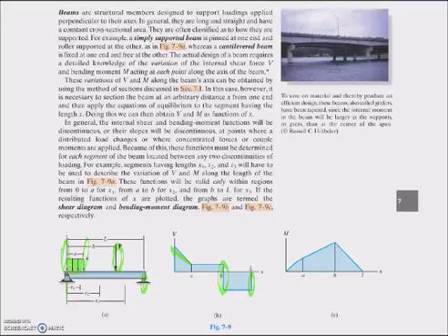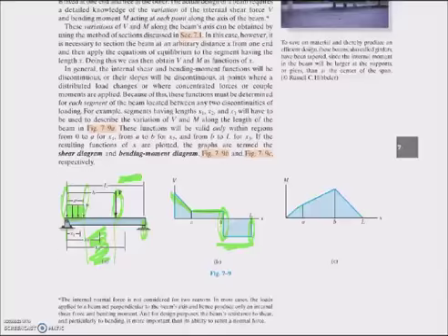But in between, right in here, where there is no change in forces or anything like that, that says that the shear doesn't change in between these two points. And you can see that that is the case here, where we're between applied loads, the shear is constant. The same thing between here and here. And then we see that right here the shear is constant between those points. And we'll talk a little bit more about moment as we go.